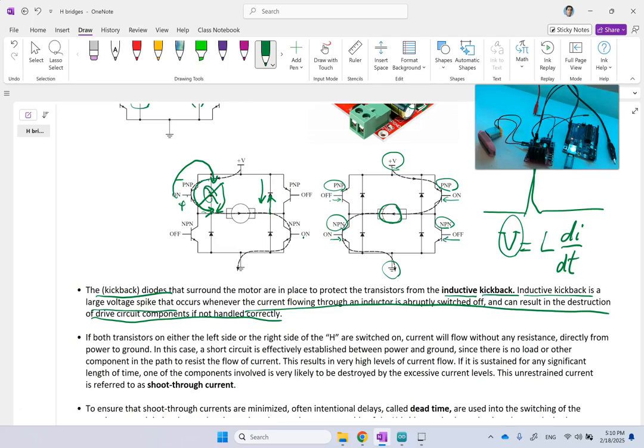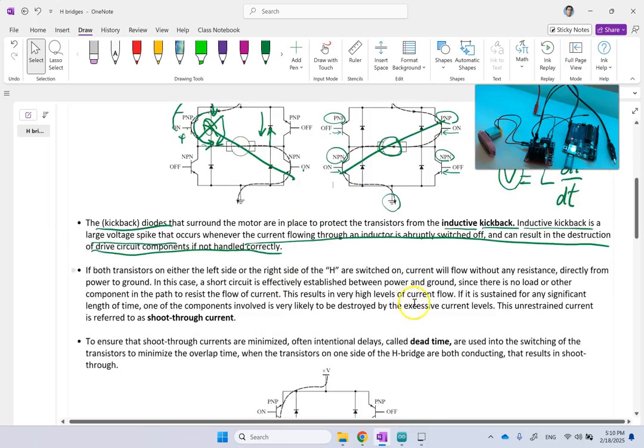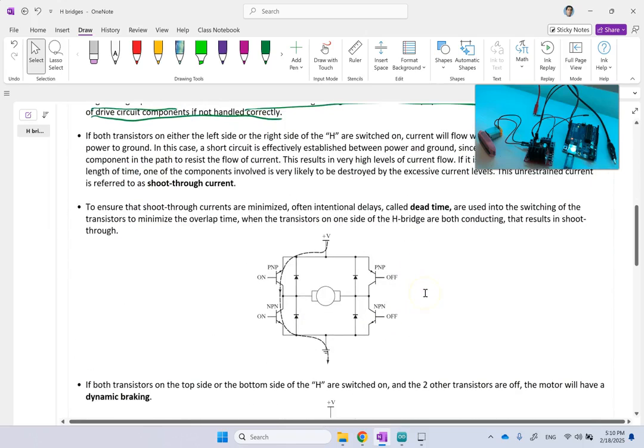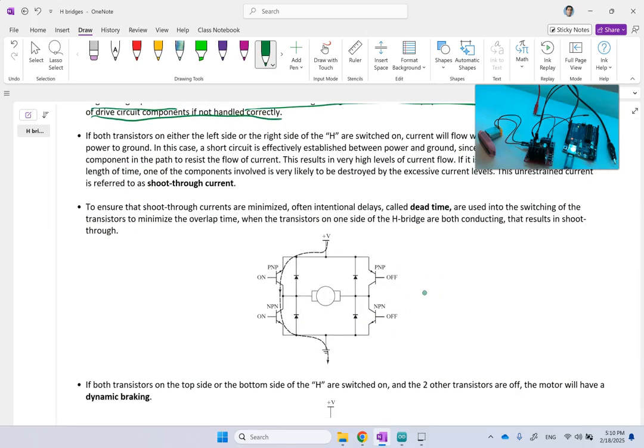So more discussion of why we put them the way it is, I can talk about in an upcoming video about transistors. So let's postpone that for now, but just know that on the high side, PNPs, on the low side, NPNs, and by switching the 2 that are in front of each other in either direction, I can switch the direction of rotation.